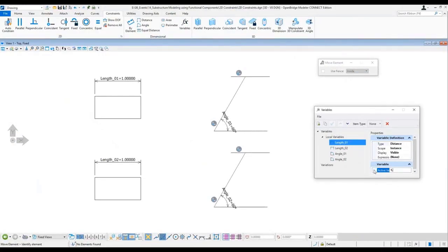The fixed constraint can be assigned to a node or line for a working point or for controlling movement. Even though you assign it to a line, the line can move by dimension because it only restricts the angle of the line.